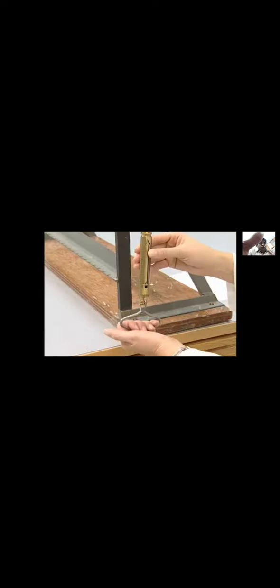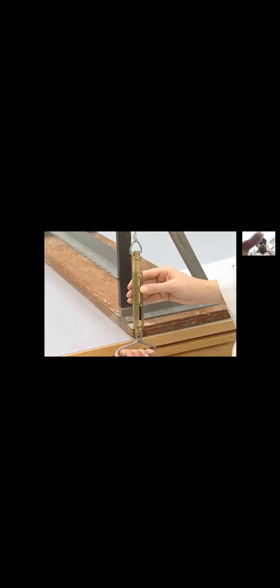A ruler, graduated to read percent, is attached to the center of the upper middle benchmark. Then, attach a tensiometer to the lower hanger assembly and pull the indicator cycle between 0 and 5 pounds force, comfort stretch, 4 times, for a cycle of 4 to 6 seconds. The 5th time, pull the tensiometer to the 5-pound force level and hold for 5 to 10 seconds. Then measure to the nearest 1%.